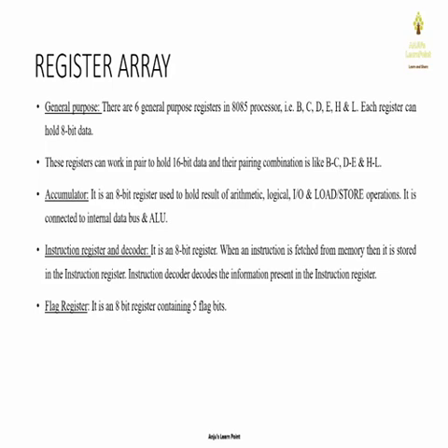Next is the accumulator. The accumulator is nothing but an 8-bit register that can hold the result of arithmetic, logical, input output and load store operations. It is connected to the data bus as well as the ALU, because whatever operation is happening in the ALU, the result will automatically be stored in the accumulator.